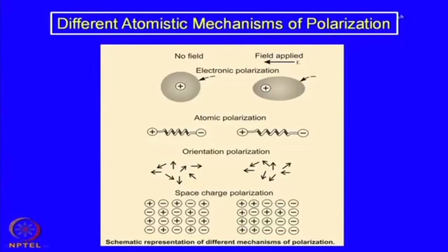So, dipole moment is 0, that is the normal concept. But when you apply an electric field, there is a net distance of separation; the center of positive charge and the center of negative charge distribution throughout the material get separated, and you form a dipole, and that is what has been given here. There are 4 distinct mechanisms by which dipoles can be generated.